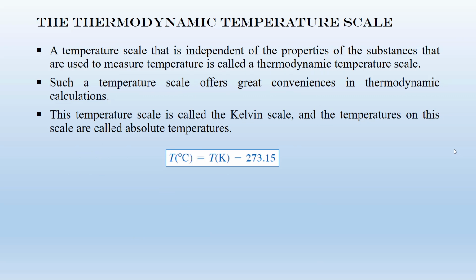Okay, so in engineering, normally we use the absolute temperature for calculation. We already discussed it in chapter 1. The absolute temperature in SI system is Kelvin, and in British one is Rankine. So it's possible to show that the QH over QL for reversible process, this ratio equals the TH over TL.